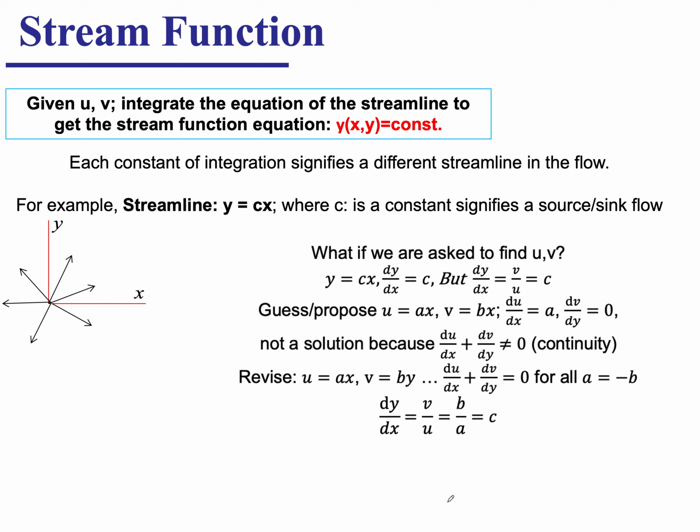Welcome to Aerodynamics. In the previous lecture, we looked at a group of streamlines that are issuing from a point source. And that group of streamlines, line 1, line 2, line 3, can be classified into a stream function. So a stream function is just a group of streamlines. So we will denote the stream function by psi.